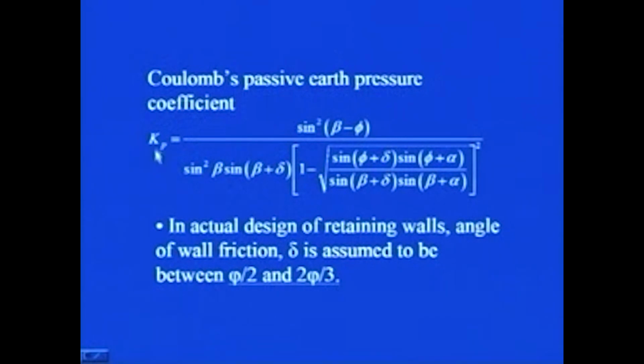Where you see here, this is for inclined backfill, you have this long expression for your Coulomb's passive earth pressure coefficient. Then again I will show you some of the values which are available in standard textbooks. You do not have to remember all the time this long and lengthy expression.